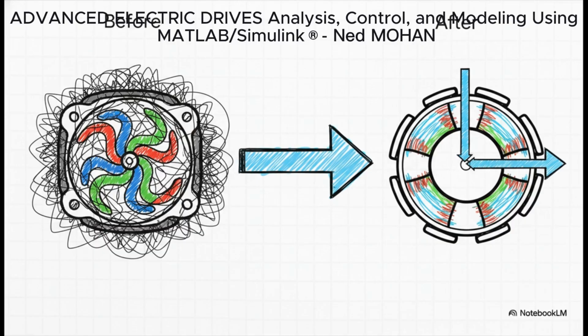We can now analyze the entire machine as if the stator only has one winding, and the magnitude and orientation of that one winding are just described by our space vector. This just massively simplifies everything, how we visualize it, and, more importantly, how we calculate it.